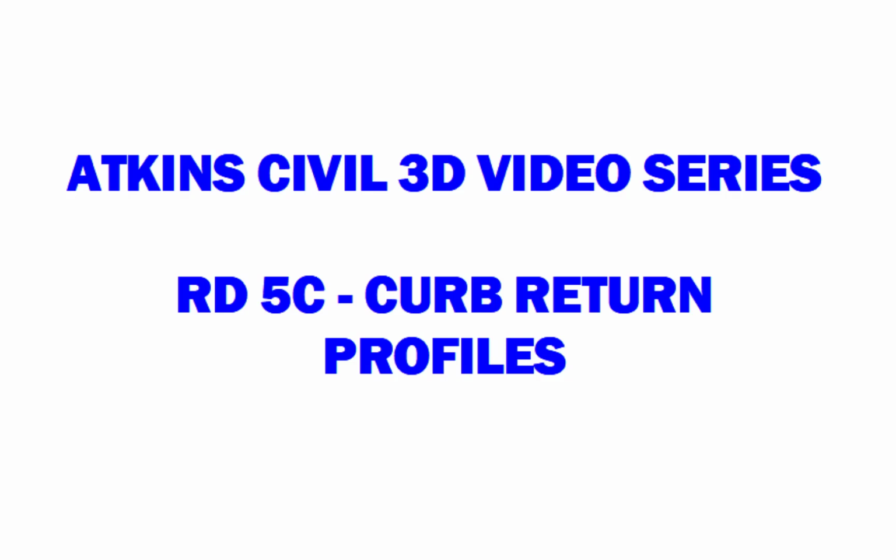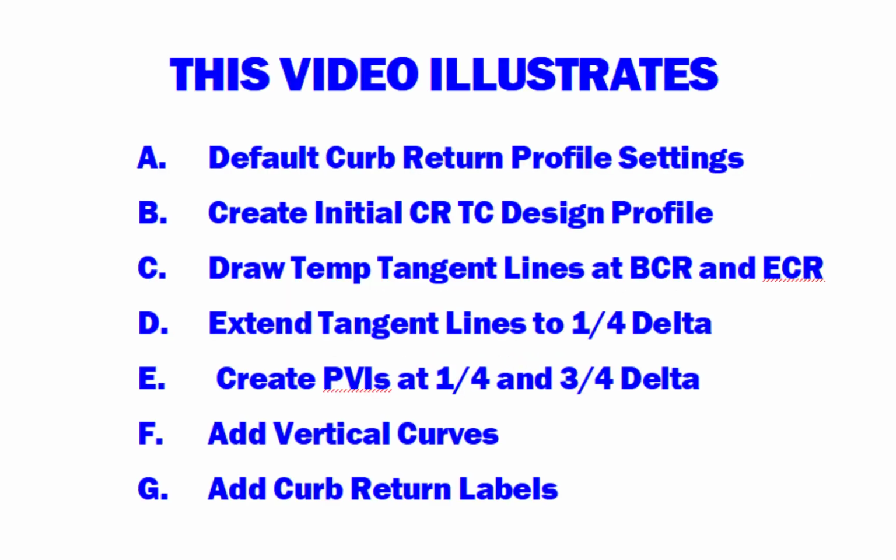Atkins Civil 3D video series, Road 5C, curb return profiles. This video illustrates A. Default curb return profile settings, B. Create initial curb return top of curb design profile, C. Draw temp tangent lines at BCR and ECR, D. Extend tangent lines to 1/4 and 3/4 delta, E. Create PVIs at 1/4 and 3/4 delta, F. Add vertical curves, and